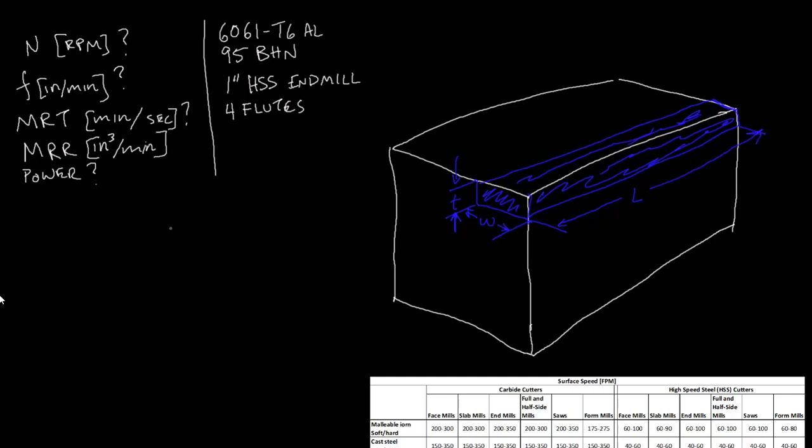So let's put some actual values to those. I'm just going to switch my pen color. So let's just say this is 0.1 inches deep by 0.75 inches in width, and let's say this is over the 6-inch block. So that defines our step in here. So then we're going to draw the cutter here.